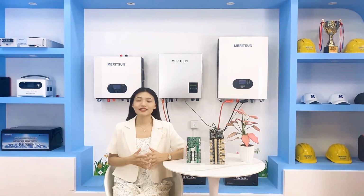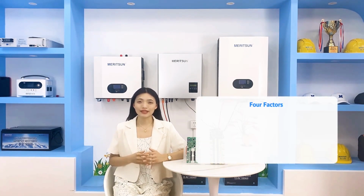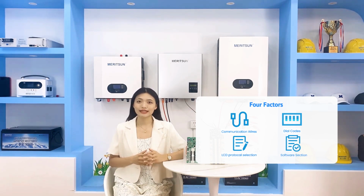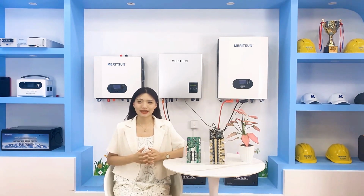The factors that affect the communication between inverter and batteries will be divided into 4 factors, which is mainly 2 aspects. One is the hardware section, which includes dialing the code, protocol selection, and the communication wiring. The other section is the software section, which mainly involves whether the protocol exists and is selected on the software of the BMS. Let's start with the hardware section.